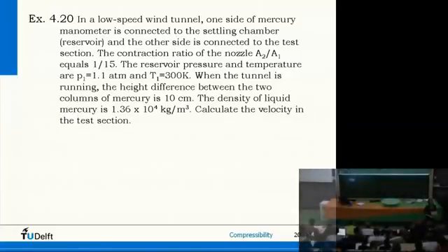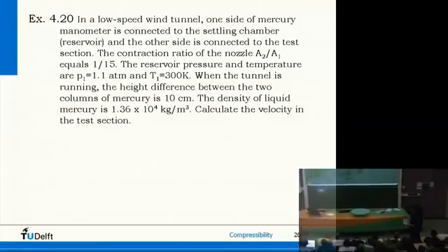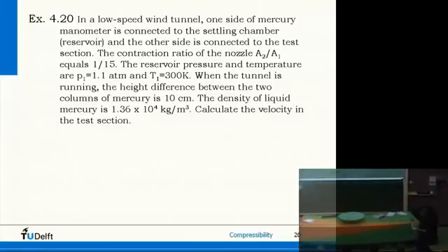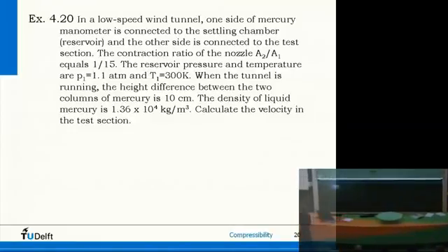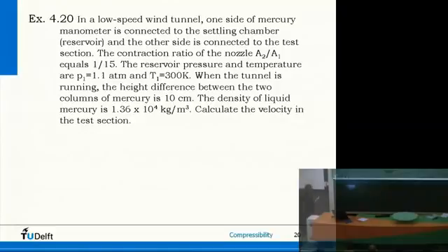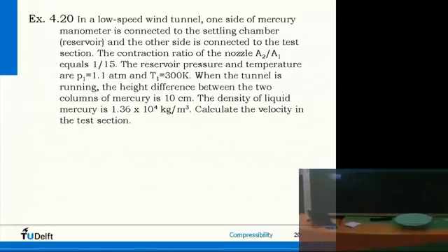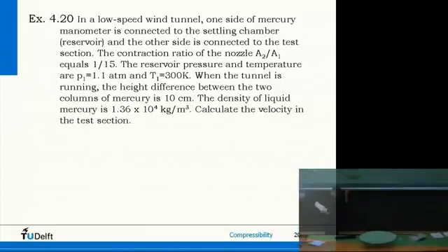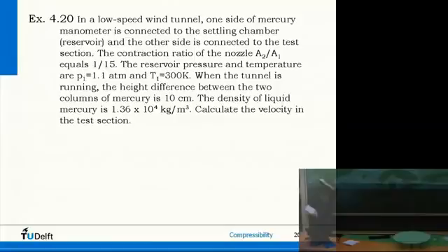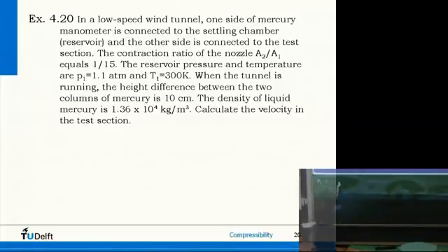I put the manometer on, right? And it's P1 minus P2 with a height. How did I know which one was the low pressure and which one was the high pressure? I think I said P1 minus P2, or did I say P2 minus P1? P1 minus P2. So here was rho g h.